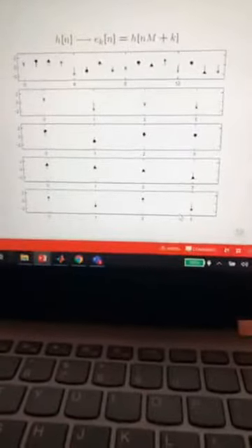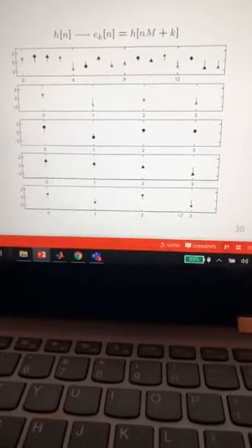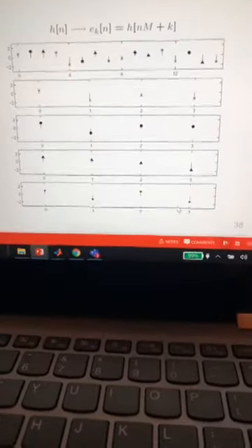And systematically, you are not computing the sample which is not required in your computation. But remember, in IIR filters you have to use the previous sample. IIR filters: y of n is equal to a1 y of n minus 1 plus a2 y of n minus 2.